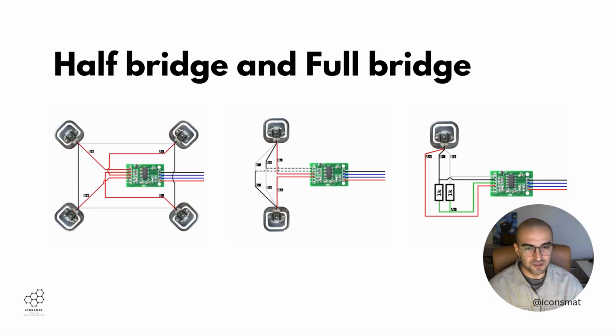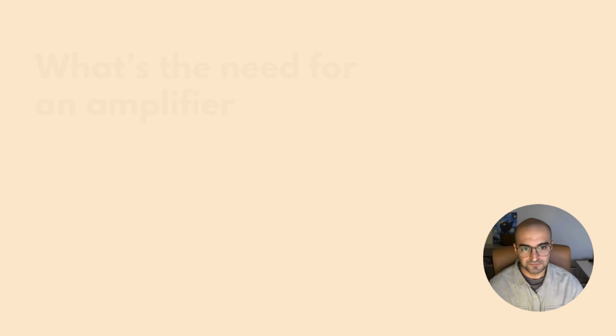A half bridge is also a form of an acceptable load cell design, but the right side circuit design is not accepted. Although it works, be aware that when temperature changes, your readings will be totally faulty.